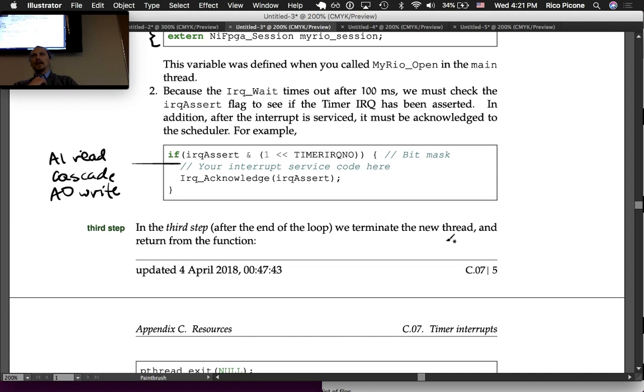So you can get around that by timing or estimating how much time your other tasks take you, right? So you can do that. But where you run into trouble is if the amount of time that each task takes is variable. Like in the case of the speed function, when you hit the button and it prints to the screen, that takes longer than the other loop did. Printing to the screen took longer. So if your timing gets screwed up, then not every BTI is actually the same. And so that's where the wait function has a lot of limitations.